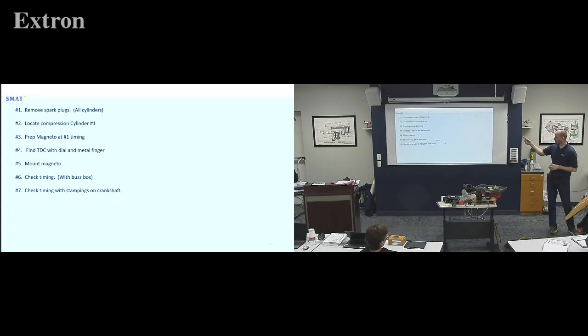Alright, so I'm going to do that one more time without any explanation in between, just to make sure you guys are following me. So, I have no idea where I'm at. I'm going to put my thumb on here and rotate forward until I get where it tries to push my finger off. Not yet. Not yet. Okay, that's my compression stroke. So on my compression stroke, it's half cut. I put my finger in. I'm going to come forward till I hit it. Put it to top center.